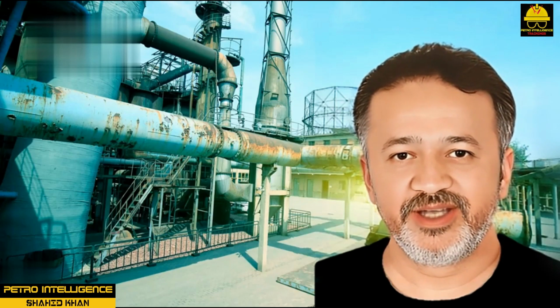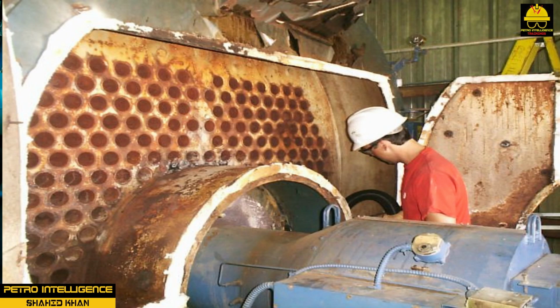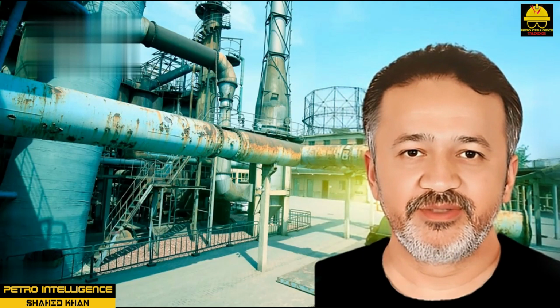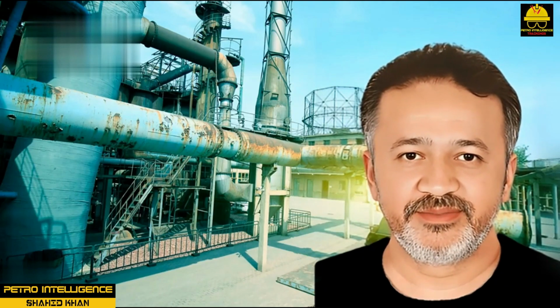Corrosion. The process of corrosion is a complex electrochemical reaction that can attack a large area or a small pinpoint area. Corrosion in a boiler is typically associated with the reaction of oxygen with the metal. However, pH, a measure of acidity, stress, chemical compounds, and other factors can contribute to corrosion. Corrosion may occur when the boiler or boiler feed water has excess acidity or alkalinity, high levels of oxygen and carbon dioxide, high temperature, stress, or high levels of ammonia or sulfur-bearing gases.